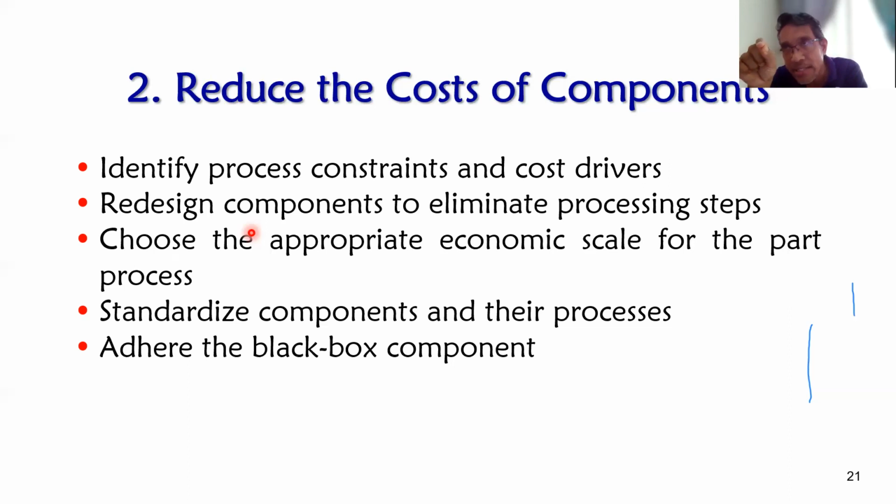So we can eliminate the step if we combine this step with another alternative step. So that is how we think when we go to see the production. We can even say, oh, this one we can eliminate if we use a net shape process, for example. What is the net shape process? Net shape process is like casting, like forging, like extrusion. So we use that process, we have a final, intended geometry in a single manufacturing step.